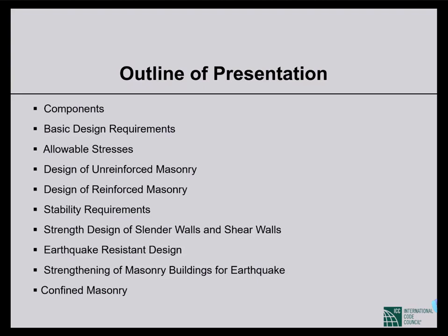Considering a boundary wall, what should be case 3 or case 5? For a boundary wall, if we have stiffening members and it is continuous, then, on slide 8, you mean for effective length, right? Yes. It will be the continuous case if you have stiffening members. All the pictures will actually guide you.